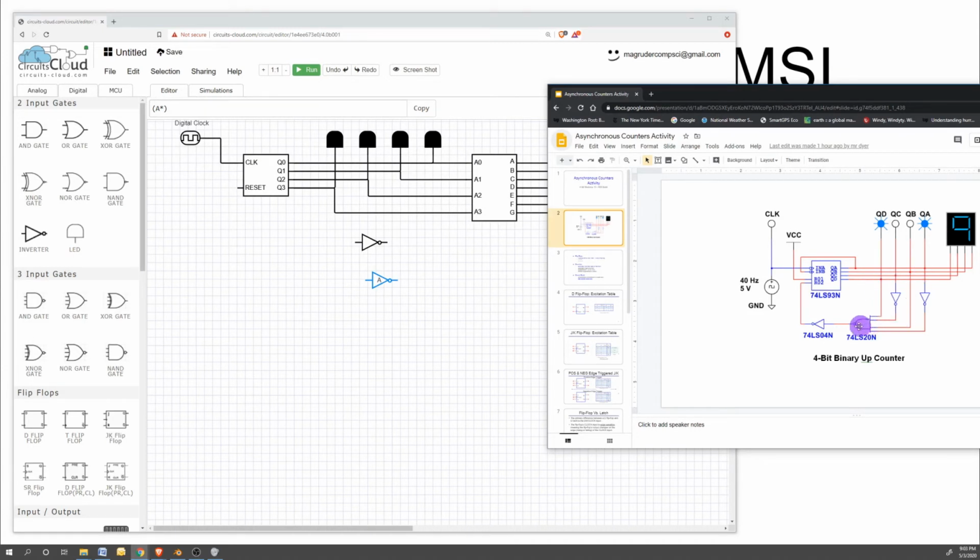We're going to take those signals and provide the logic so that only in that one combination is the reset toggled. The reason it's done with the NAND gate in the original design is it's a very convenient way to get a very specific combination of values. Notice they're having to double negate it here to flip it back into the actual toggle, but this is pulling a very specific combination from these wires. In this case, where it would otherwise be reading A in hexadecimal, or the binary value 1010. And so this is what we're going to implement last.